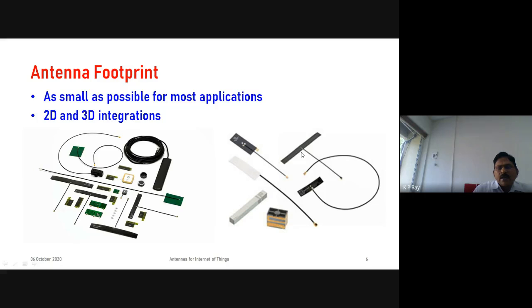And then the input impedance, in the case of bounded media, has to be modified so that it will match the transmission line. Otherwise you will lose lots of power in the form of reflection right here. Instead of radiating full power, if it is not properly matched, not properly integrated in the bounded, interfering media, then you lose lots of power in reflection, because the input impedance gets modified, and only the remaining power you will be able to radiate for the intended application. So these are very, very important aspects of these antennas.